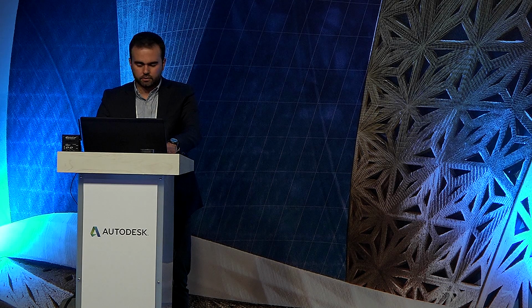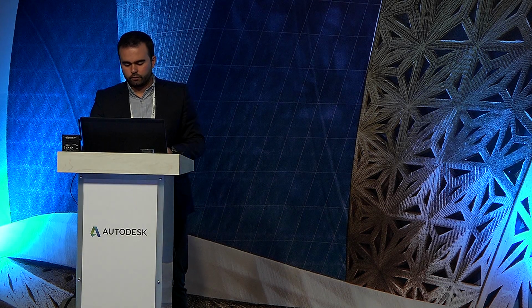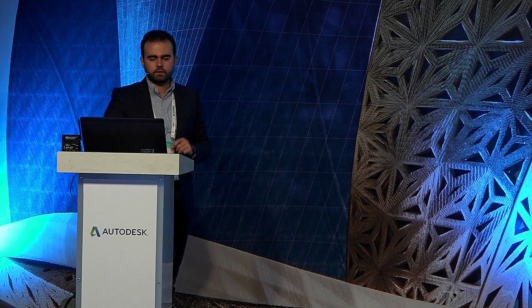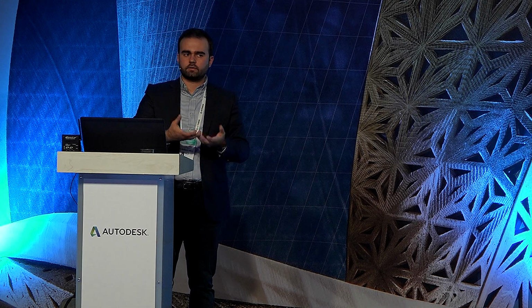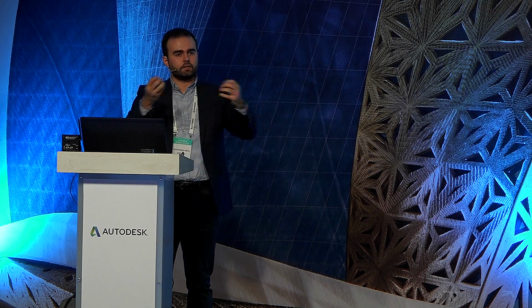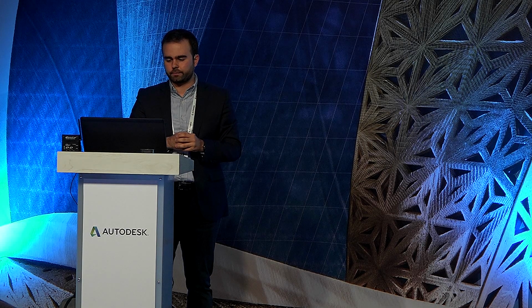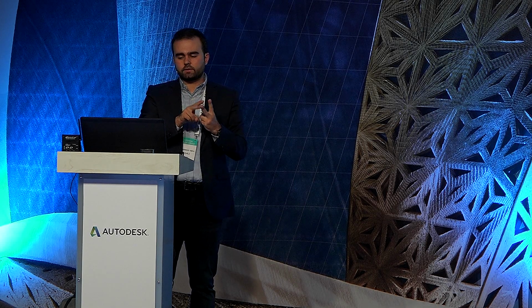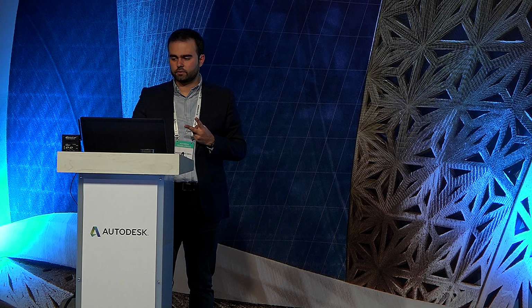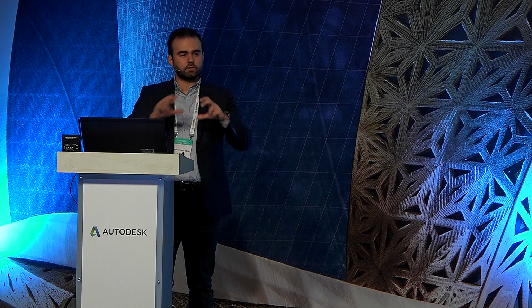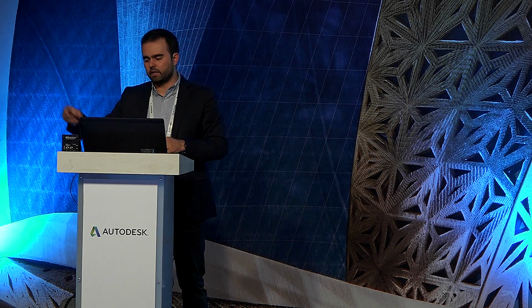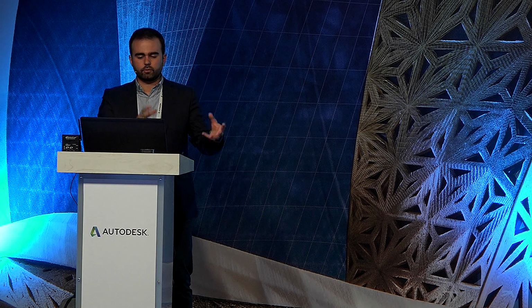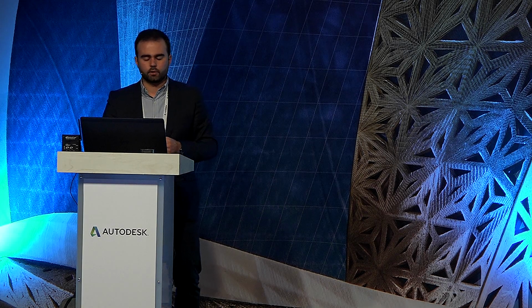And let me just show it to you. So whenever we talk about reality capture, sorry, the title is not shown. I wanted to talk about reality capture. So any act, any event of capturing existing conditions is called reality capture. Reality capture is two ways. Either the laser scanning, which is using these scanners, or as I mentioned, photogrammetry. We send a drone with a DSLR type camera to take those pictures, and from those we can create 3D models.